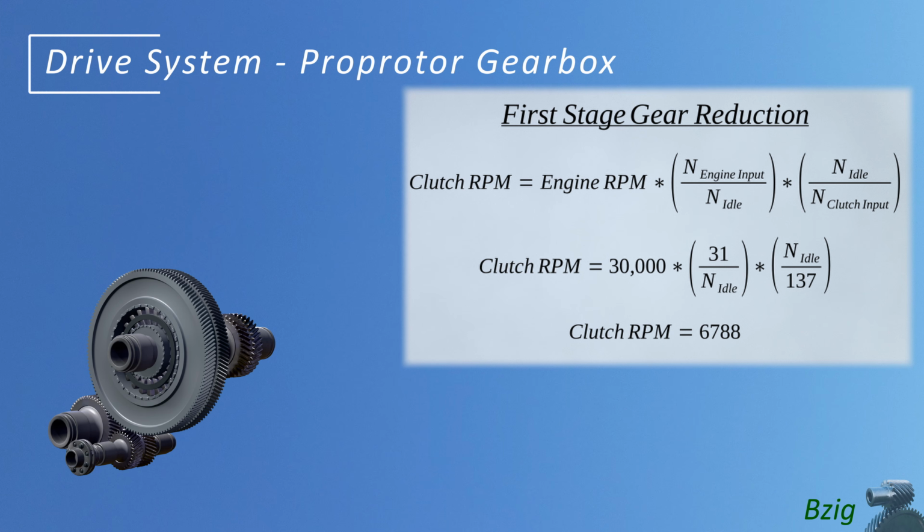Interestingly, the number of teeth on that extra left-hand gear doesn't alter the gearing. The idle gear tooth count appears in both the numerator and the denominator, so it cancels out inside the equation. Because it doesn't change the RPM, it's called an idle gear.